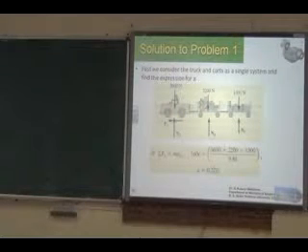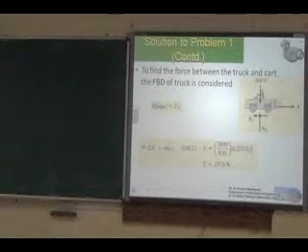You have to find the force acting on the coupling between the truck and car A. Now you have to draw the free-body diagram for the truck, then go for finding the force. First, by using Newton's law, we have found the expression for acceleration. The force is 160t, on the right side is mass times a, not t.